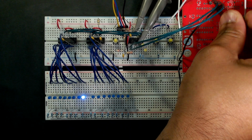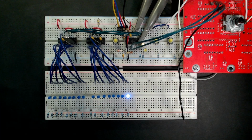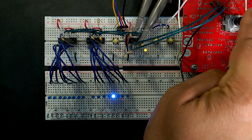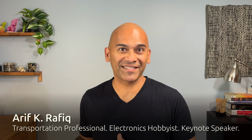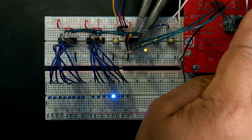It's beautiful, isn't it? An incredibly responsive rotary encoder that's controlling a 16-bit indicator display. Not just that, but there's 3 buttons which instantly go to a particular intensity. This is precisely where we ended on the last episode, where we leveraged the analog to digital conversion peripheral of the PIC microcontroller to interpret those various different button signals into one pin. These buttons generate a different voltage, which is interpreted by the microcontroller to a single digital value, and that value is an intensity level for illumination.